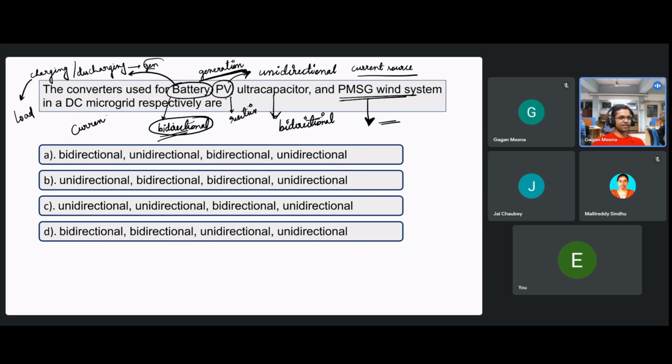So they have a bidirectional current capability requirement because when they are charging, current is in one direction and when discharging, the current is in the other direction. And also this P and Q they can inject or even absorb based upon the switching pattern.